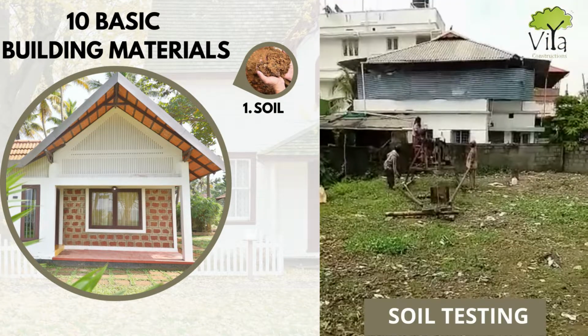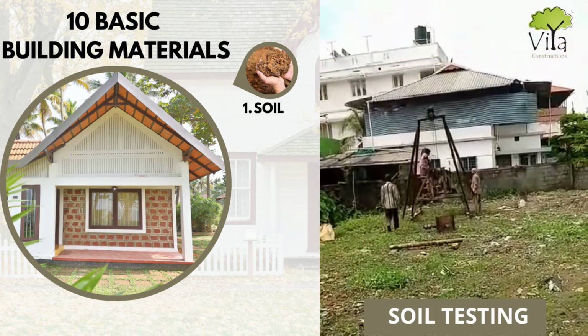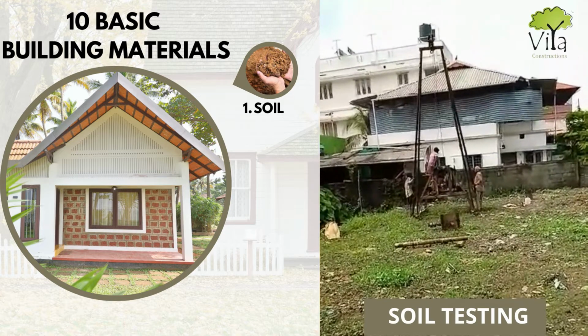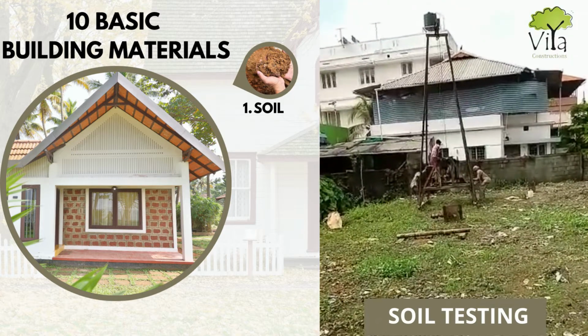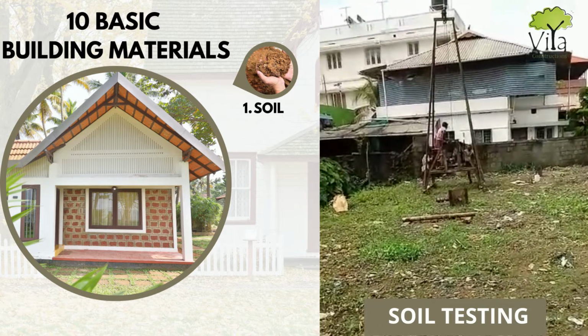The most important soil characteristics that affect the foundation are the water content, presence of vegetation or remains of cut trees, landfilling and proximity to mining areas. Soil testing should be done in detail and by a qualified agent before the start of construction.